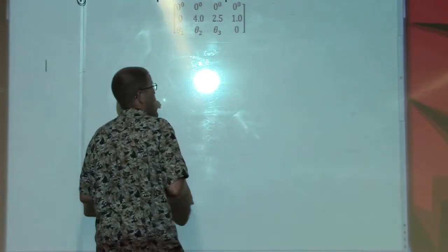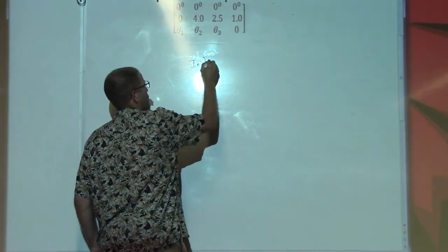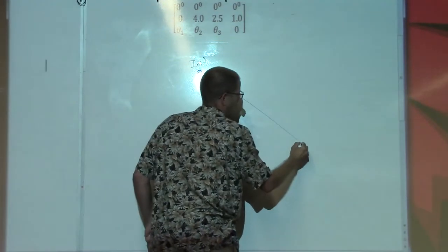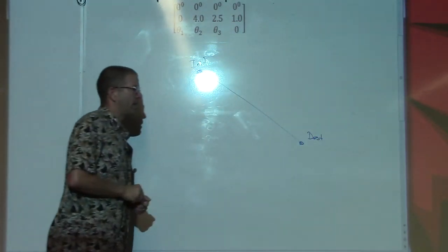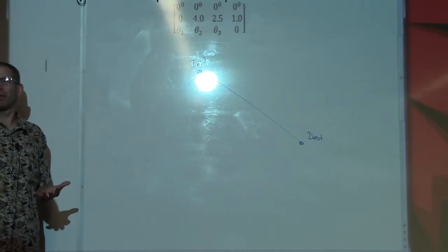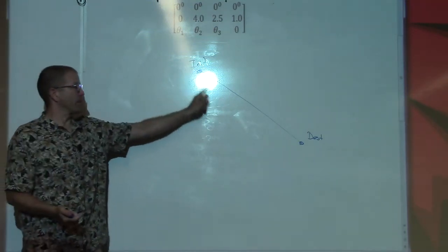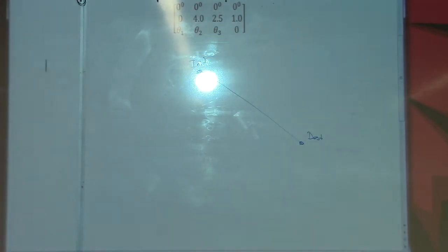And I'm going to exaggerate this a bit more. So we have our initial position here, and we have our destination. And let's say that we want to take 200 steps between the initial position and destination, just because I'm kind of stuck on 200 for some reason. It's what we used last week for our motion, it's what we'll use this week for our linear interpolation algorithm. Can we just take the total distance and divide it by 200? Yeah, absolutely.